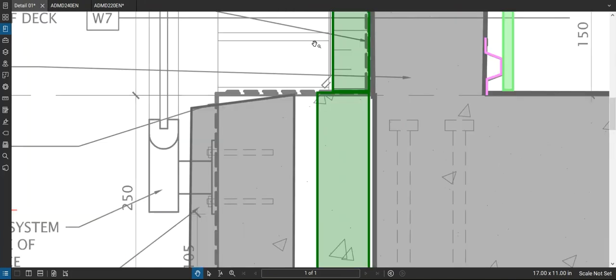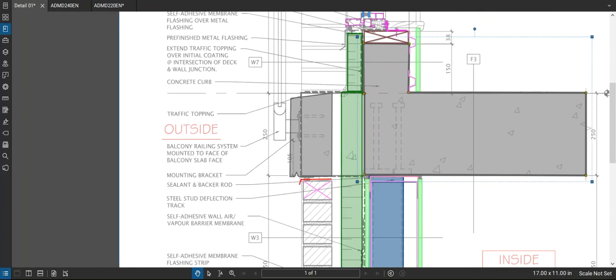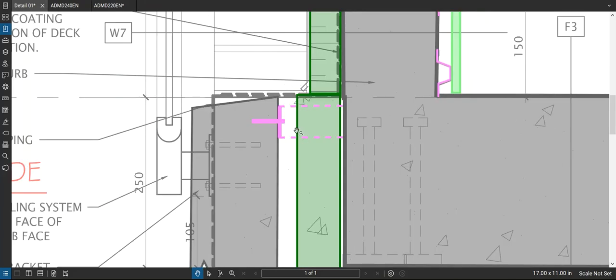And pinning the top of this thing here, you could just pretty much have a brick tie type scenario with a flange, kind of like an L angle flange, where there's an L coming out towards us here, and then you could anchor back in like that. So that'd be pretty easy to come up with something to pin the back of that stone there. And you want to think about accessibility there too.